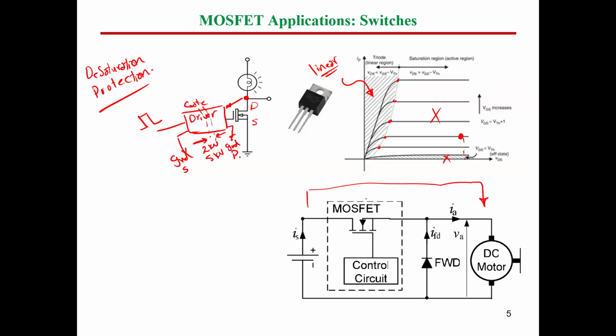So you will have a very small amount of volt here, which is the V drain to source volt during linear operation. But this volt is very small compared to the supply volt and the motor volt, so this can be neglected actually. So guys, the supply volt will be applied to the DC motor here.